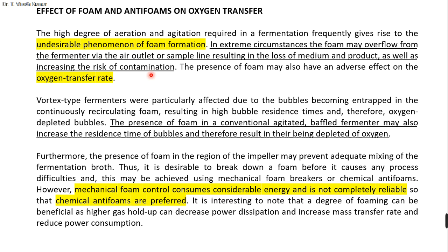Previously, mechanical foam controlling machines were used that rotate on the top, or otherwise the foam may be collected from the fermenter vessel and ground by a blade, like a mixer blade or a homogenizer, and after removal, the foam is poured back into the fermenter vessel. This will create a lot of complications. Sometimes this may create contamination also.